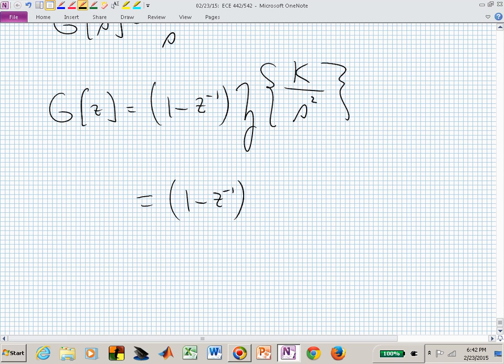We now had the table out. We looked at table row 6. We looked at row 8. Now we go between and we look at row number 7, and we find that the Z-transform of a 1 over s with a k in there is k capital T z over z minus 1 squared. You need to go home and make sure that you're comfortable with where these are coming from. This is not magic, it's from the table, but next time I think we might derive that expression.